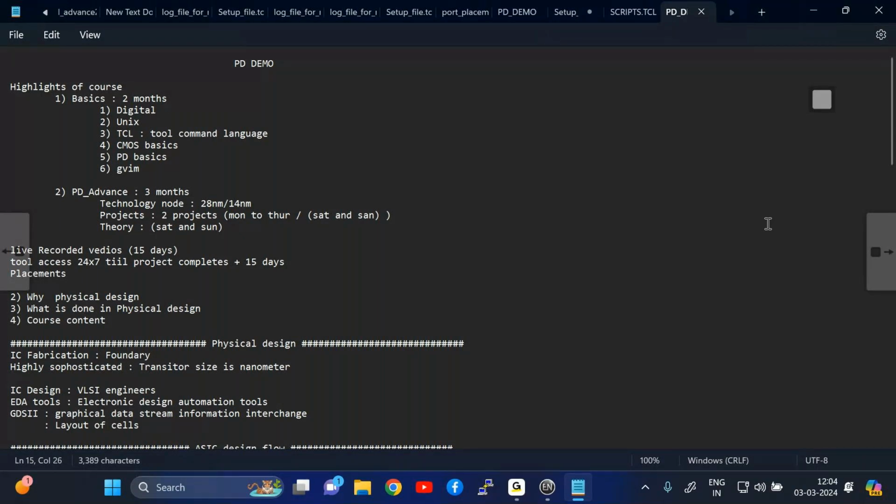But those who create the macros would have followed some method. For example, for an analog macro, they will directly draw the schematic, because they cannot write Verilog code for it. If you purchase an analog macro, they will draw the schematic of an A to D converter or your PLL, draw the layout for that, and give it to us.